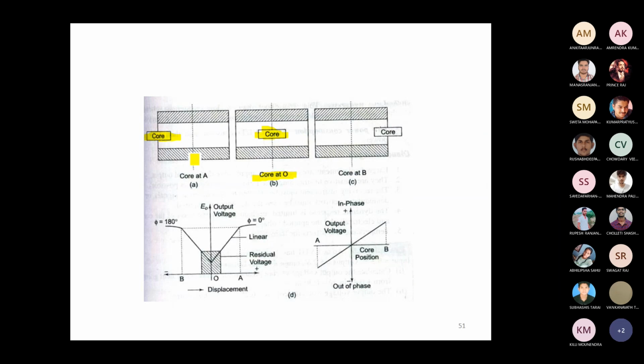In these conditions, there is a negative point. VA is zero, basically because there is no cutting of flux by the core. So at this negative point, VA minus VB, where VA is 0 and VB has some value, we start from a negative voltage. You can see there we start from some negative voltage. Then only the positive side remains. The negative side is 0, so no cutting of flux, and directly the positive side follows.